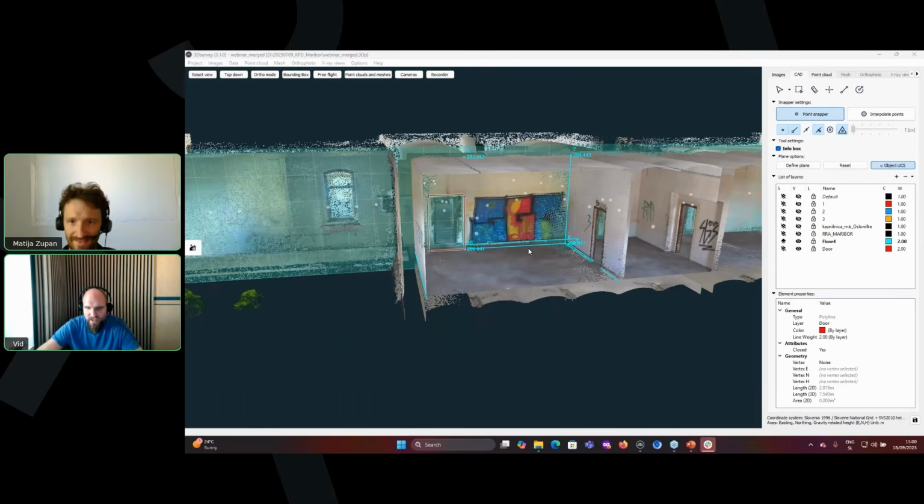I'm not 100% sure yet, but with a few models that we saw, when you went inside, you would not get accurate data. I think the reason was that they make the scanners cheaper by leaving out the INS, the Inertial Navigation System unit inside of the scanner, and they rely on cameras instead for this part of the job. I did see some customers also send me data from their scanners, and for example, the vertical walls would not be vertical and these kinds of things.